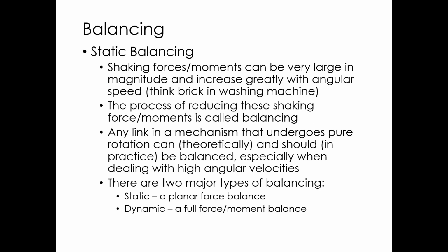Okay, static balancing. So we've talked about shaking forces and moments, and we saw that the shaking forces could be quite large. If I have a pendulum that's spinning about some fixed point and the center of mass is offset from the center, as this thing rotates around, there'll be a shaking force. So anytime I have an eccentric weight, there's going to be a shaking force, and I need to try to balance it if I want to reduce those shaking forces. The forces usually go up with omega squared, as we'll see when we get into the math. So as things go faster, the need to balance increases drastically.